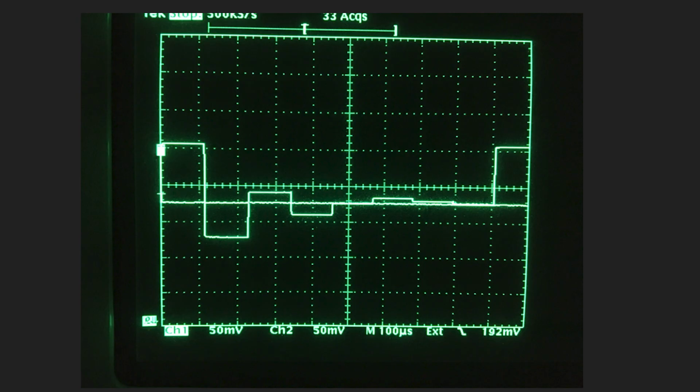So it's a fairly accurate circuit. Obviously, it's not going to be perfectly accurate. You would need more bits, but 7 bits does give you a fair bit of accuracy. In this case, the binary value that would be shown on these display LEDs would be a 0, 1, 0, 1, 1, 0, 0, depending on whether the reference voltage is less or greater than the sample voltage. If we take a fraction of that over 127, or just a binary 1, 1, 1, 1, 1, 1, 1, and multiply that by a reference voltage, which is 5 volts, we get 1.73 volts, which is within a very acceptable range of 1.74 volts.